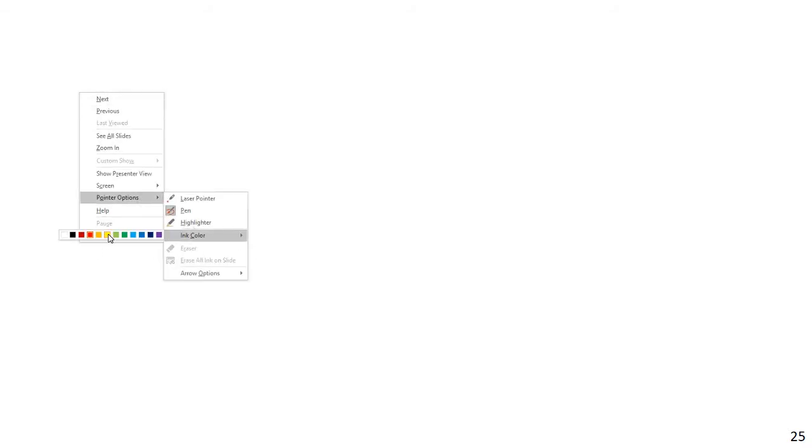So here, how do we know whether we're in the short or the long LD case? The short LD case is going to be better. You need less development length. Basically, by default, we're in the long case unless we can meet a particular set of criteria, two potential sets of criteria.